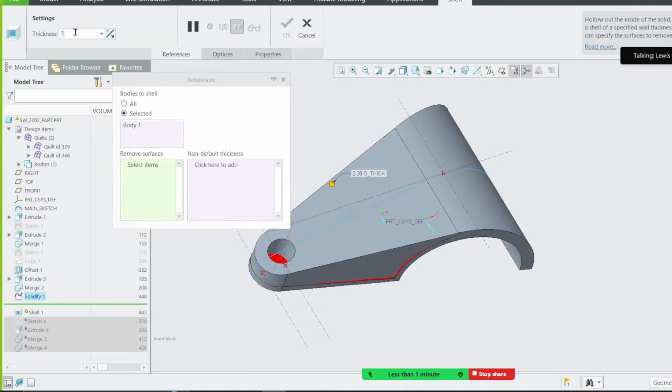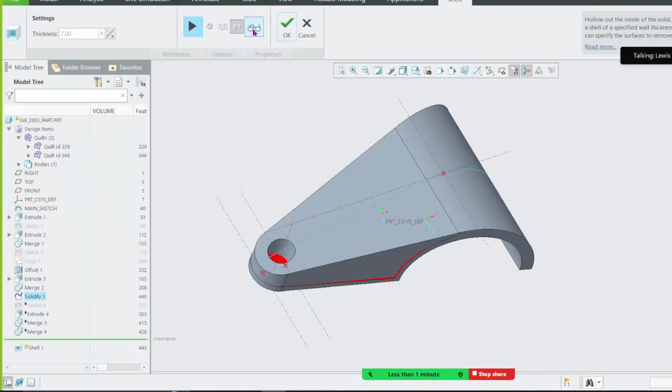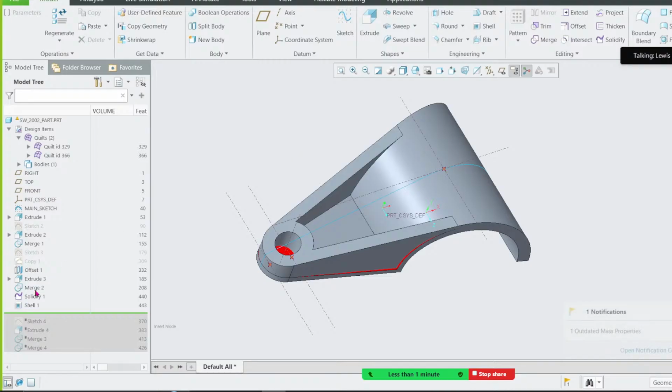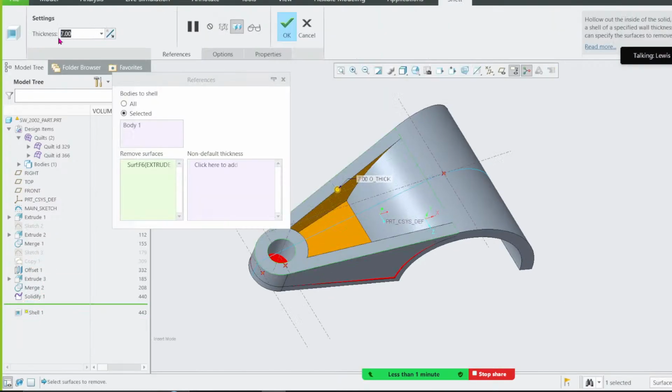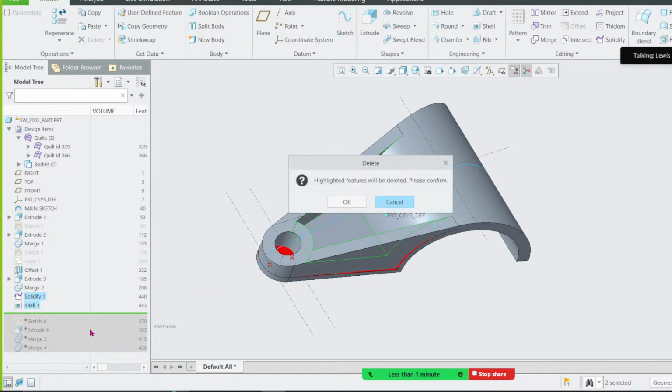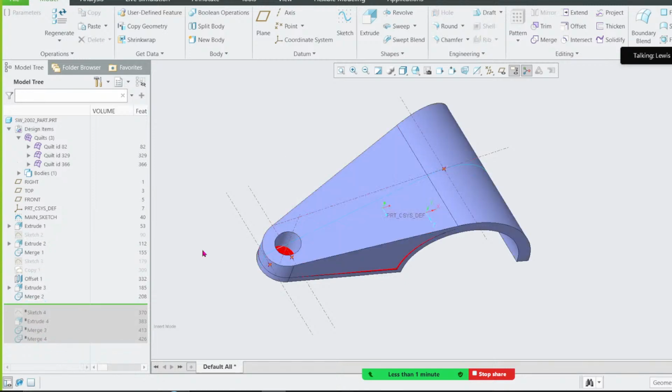And I'm avoiding dimensioning things. If I say shell this surface here, I'm putting a dimension and I have no control of that dimension. It is inside, it is here. That's the reason why I have not used this method, because that dimension is buried inside the part.